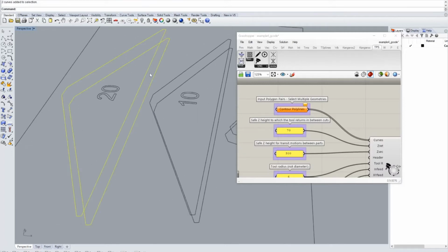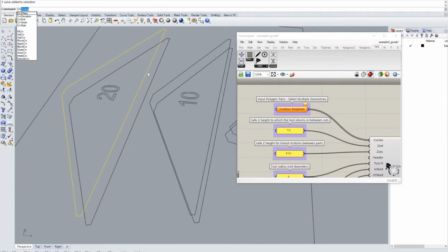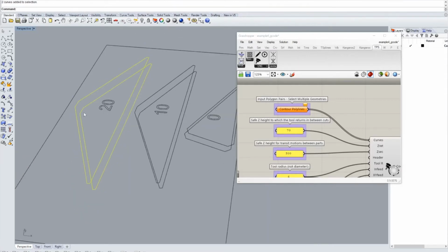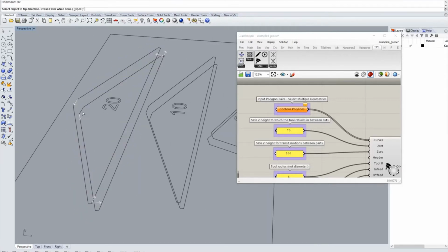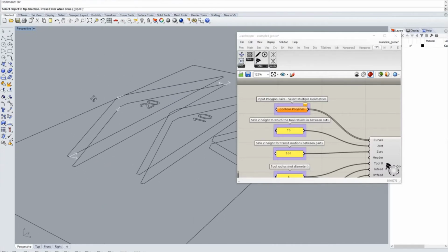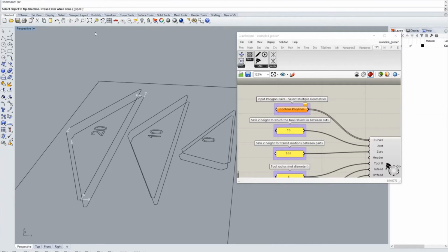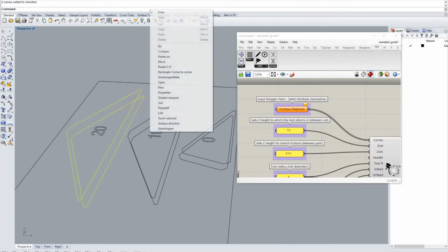If we had the situation where the start points are not looking the same, this can be changed with the curve seam command. With this we can actually change the start point of the curve. I can put it here. So now if we would go again, we would use the direction. Then you see the start point has moved. And in this case now we would actually have to use, in order to fix this, the curve seam command.